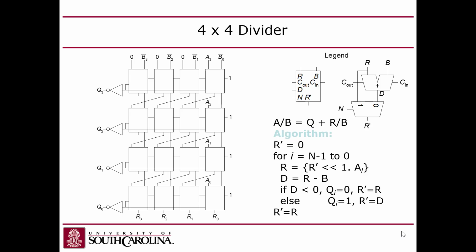How many of you found that, by the way? About half? Yeah, that was the bug, because it didn't consider the special case of comparing an unsigned number to 0. If you compared any unsigned number to 0, it would fool the ALU into thinking that the number was 0. So how do you get around that? You have to check to see if the second value is 0. In unsigned numbers, no value is less than 0, so that has to be treated as a special case. So that might be what they're doing there.